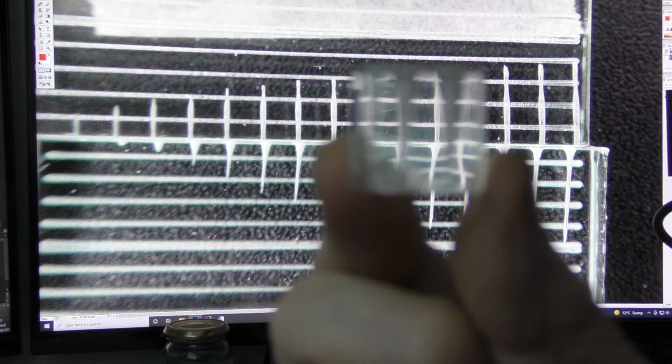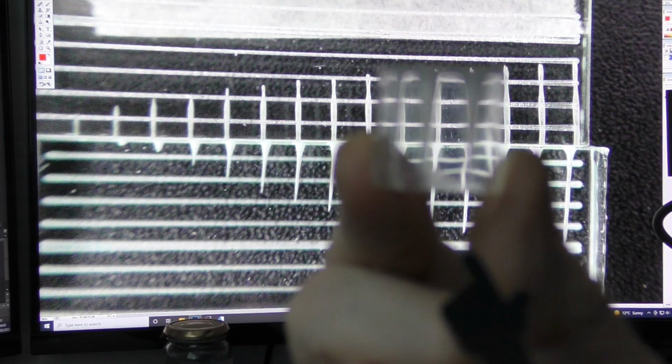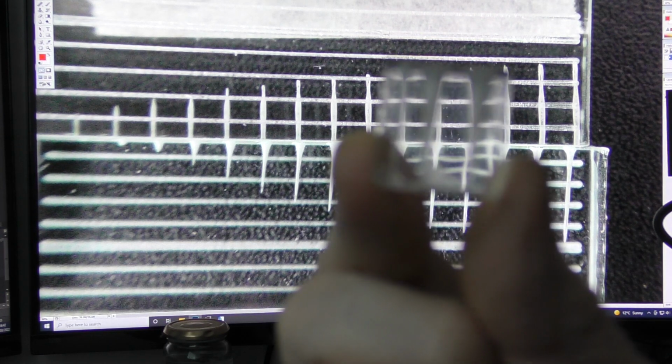Because remember, even on this standard 8 or 10 millimeter diameter beam, I've still got a very good Gaussian distribution which produces a very sharp beam. Even though this is, relatively speaking, a big diameter beam, it's still got a very powerful centre which is trying to force energy right through that low amplification section at the centre of a lens, where the lens is trying to focus these somewhere towards infinity. That's why we've got these very long parallel pipes. This is a cutting lens, even though it's a compound with a very short focal distance. You can't cut with a lens that's that short unless somehow you're letting power right through the centre of the lens to produce this effect.